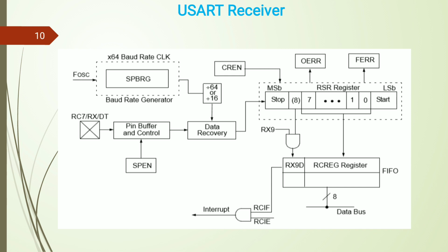Framing error is nothing but while receiving the first frame, the next frame will be overlapped with some bits, not completely, some bits, that is 2 or 3, whatever, as per the overlapping contents. So this kind of error is called a framing error. Overrun error and framing error occur at the receiver side only. There is no possibility of these two errors occurring at the transmitter side.